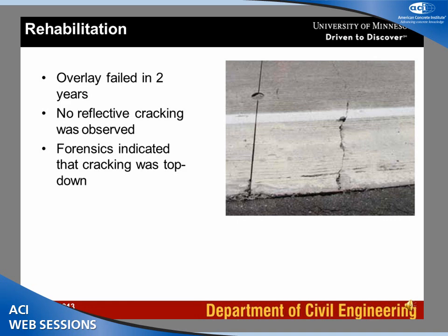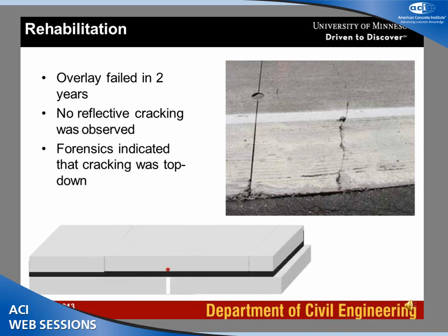But if you try to predict stresses in this location, just using Westergaard theory or using the current models implemented in the mechanistic-empirical pavement design guide, which incorporates built-in curl but assumes that the overlay does not separate from the existing pavement, you will not get any stresses here, and you always get very high stresses at the bottom. It's difficult to predict any significant stresses away from the slab, and even more difficult to predict crack propagation here.